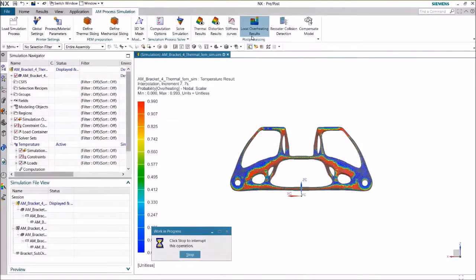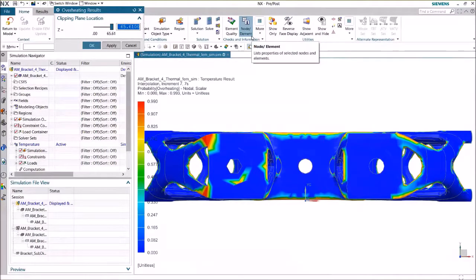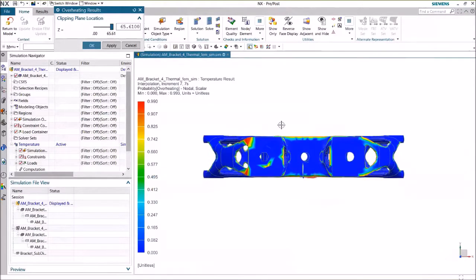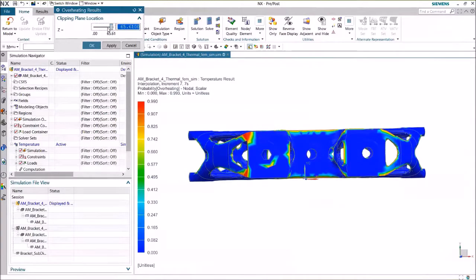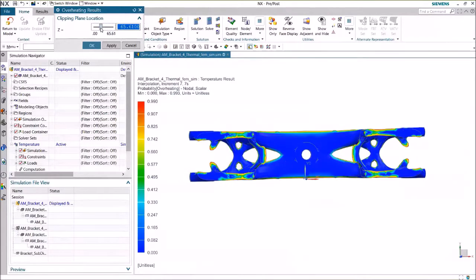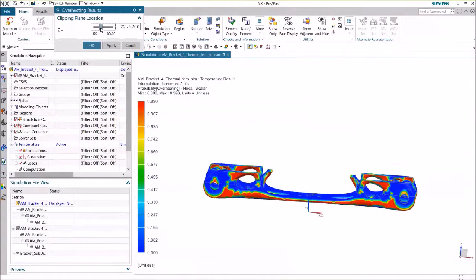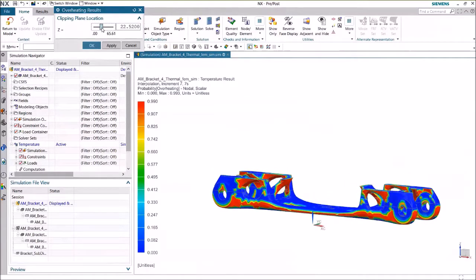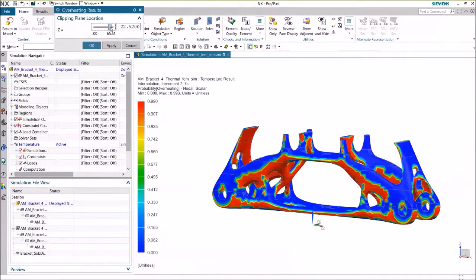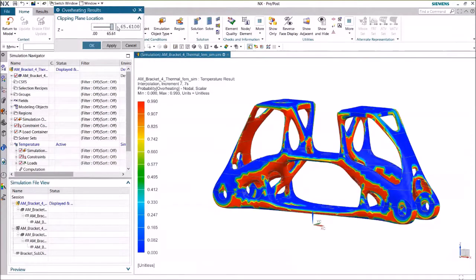Local overheating is very important information. It tells you about the quality of the surface, and the quality of the surface would also have an impact on the strength of your part and on the durability aspects. This tool predicts which areas of your design are likely to overheat and where you might want to put additional supporting or heat sink structures, or change the geometry, either way.